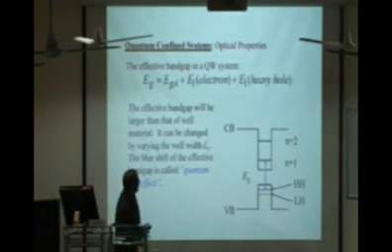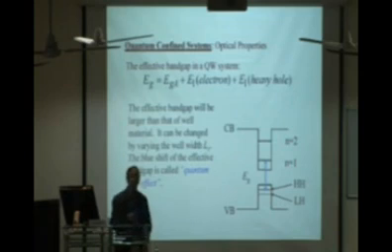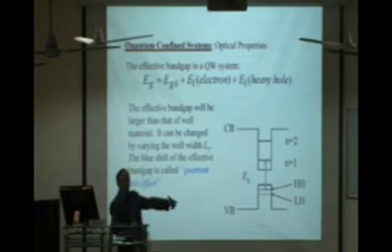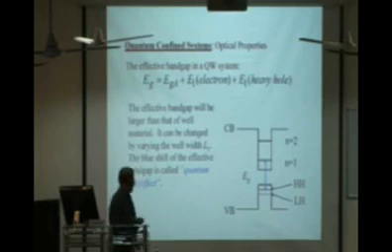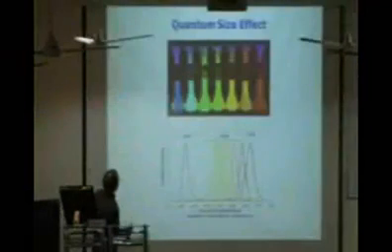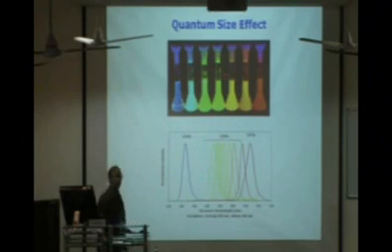That is actually one of the biggest uses of quantum mechanics: to make quantum well lasers of any wavelength. Naturally, you don't have semiconductors of all wavelengths. Suppose for fiber optic communications, only 1 or 2 wavelengths pass through the fiber optics with very little absorption. It's about 1.54 micron. But unfortunately, you don't have any semiconductor which gives an emission of 1.54 micron. So you have to alloy different semiconductors with different sizes of this quantum well so that you can get exactly the same band gap. So this quantum size effect is very important for many other applications, for semiconductor doped glass.